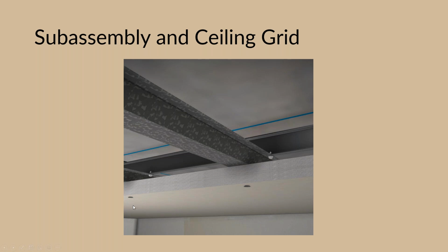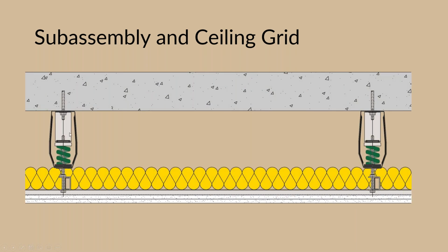Typical for a ceiling like this, you'll see 2 layers of drywall. When we put it all together, here's our slab, here's the ICC hanger, here's your cold roll channel running towards you, and here's the furring channel running the other direction, and your 2 layers of drywall. You'll typically see up to 4 inches of loose batt fiberglass in the airspace cavity.